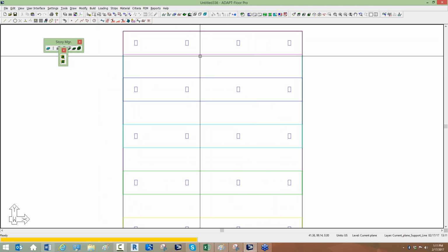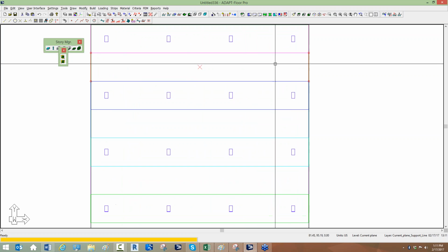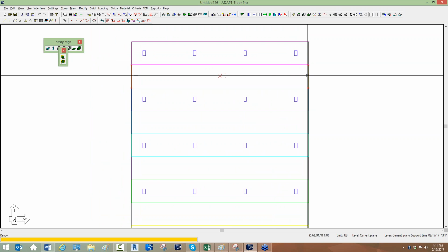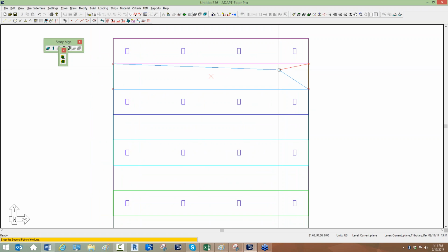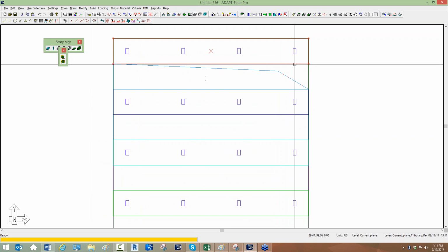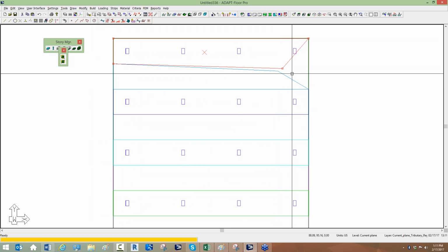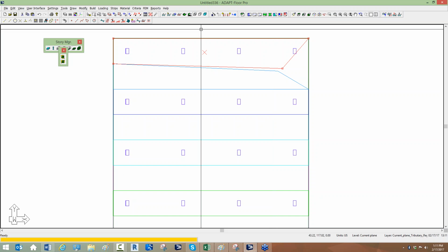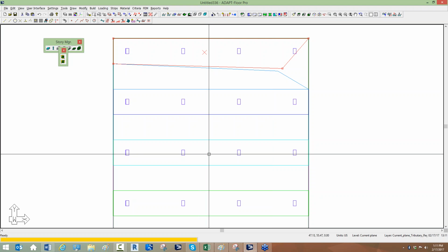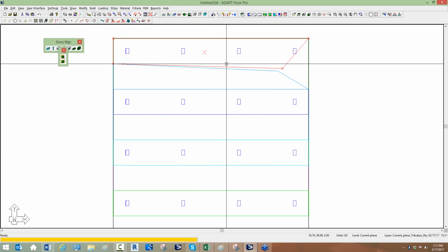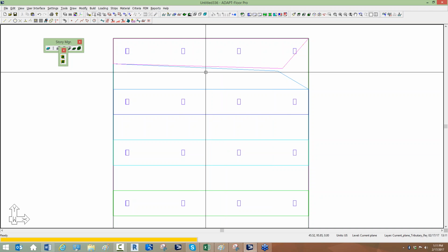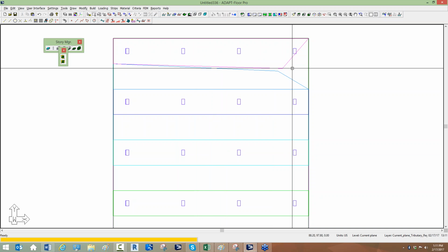If I select a region and I want to manually modify the strip, if I take this strip, for example, and let's say I move it here, and then I take this and I stretch it down over here. So I'm making some manual modifications to the strips that the program created. Once I disassociate what the program has done with what I've done manually, I can now generate the strips again, but I can use the changes that I made as the new boundaries for the design strips.